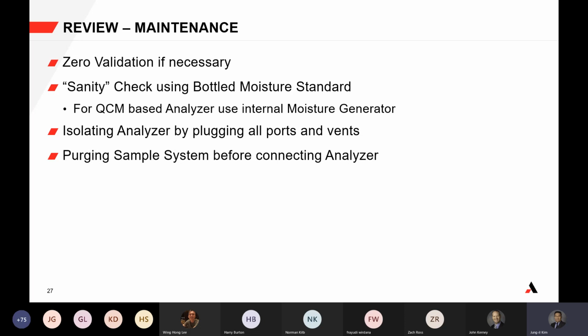So I don't think you should worry about that imbalance or turbulence when it's switching from sample to reference, vice versa, or MG to reference, vice versa, as long as you don't get the flow alarm. I hope that answers your question.